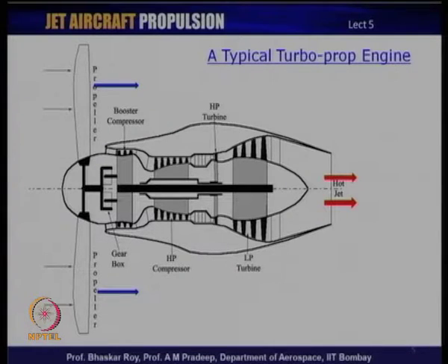Okay, so, let us start off with what can be called a basic turboprop engine. Now, a typical turboprop engine essentially is run by a basic jet engine. The basic jet engine has the capacity to produce more power than is required to run the compressor. This turbine, which is now capable of producing so much power, has, as you can see in this particular diagram, a very large number of turbines in the second group, or what can also be called the low pressure turbine group.